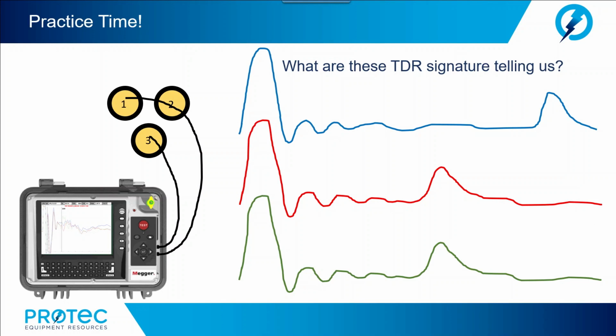All right, let's take a look here. When we connected between conductors 1 and 2, we were able to see all the way to the end of the cable termination, here represented as an open circuit. When we connected from conductor 2 to conductor 3, we measured a large increase in impedance, an upward reflection, which we can conclude to be an open circuit since we can no longer see to the end of the cable run.